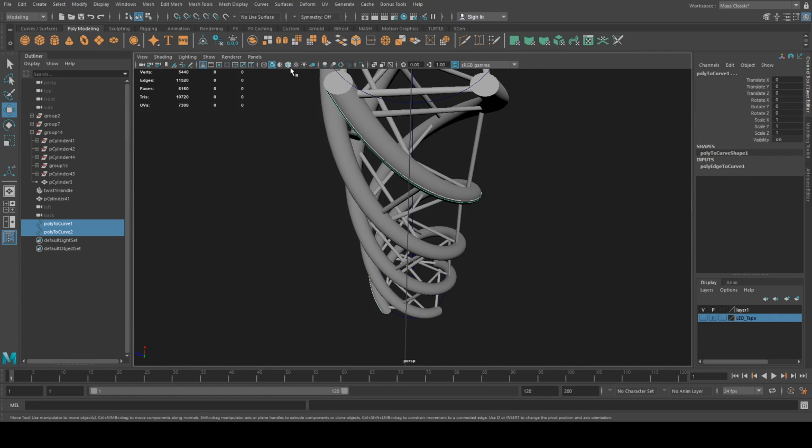Now on this curve, I'm going to go to curves, and I'm going to go to rebuild curve. And what I want to do is set number of spans. I'm going to say here I'm setting that I want 170 spans, and I'm doing 170 because I'm kind of presuming that this is like a LED pixel tape and that there's about one universe over 3 meters. So that's 170 pixels, 3 channels, 512 channels to a universe. So I'm doing about 170 pixels from top to bottom.